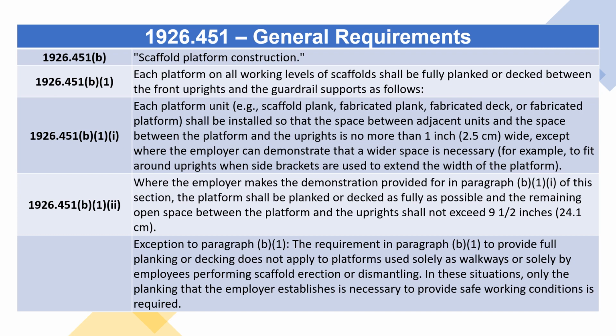1926.451(b)(1)(ii), where the employer makes the demonstration provided for in paragraph (b)(1)(i) of this section, the platform shall be planked or decked as fully as possible and the remaining open space between the platform and the upright shall not exceed 9.5 inches (24.1 centimeters). Exception to paragraph (b)(1): the requirement in paragraph (b)(1) to provide full planking or decking does not apply to platforms used solely as walkways or solely by employees performing scaffold erection or dismantling. In these situations, only the planking that the employer establishes is necessary to provide safe working conditions is required.